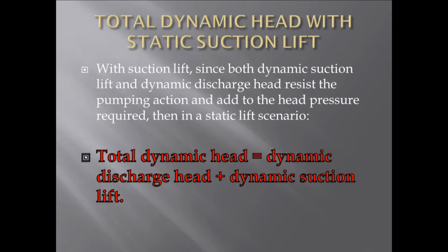Total dynamic head with static suction lift. With suction lift, since both dynamic suction lift and dynamic discharge head resist the pumping action and add to the head pressure required, then in a static lift scenario, total dynamic head equals dynamic discharge head plus dynamic suction lift.